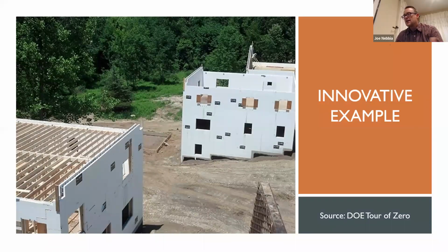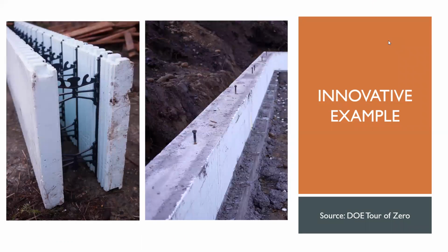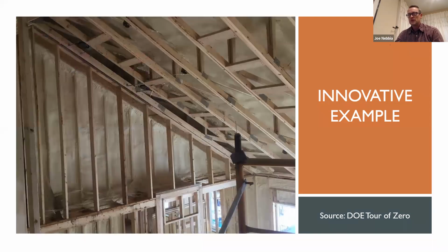This is an ICF, insulated concrete form, and this is built in blocks, and it's again 2 layers of rigid foam, and the concrete is poured in between them as it's done on site. It's incredibly strong and easy to air seal, really, really tight. This is another picture of those ICFs. Again, it's done kind of piece by piece and put together there on site.